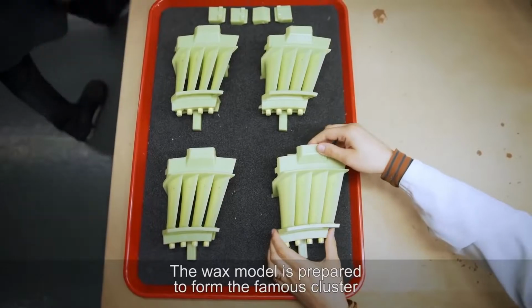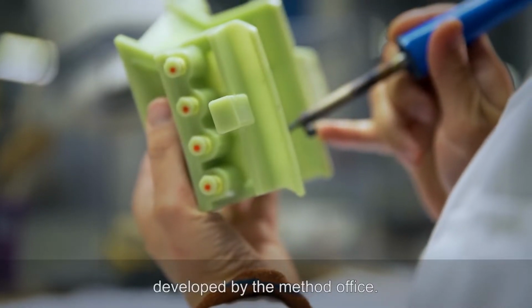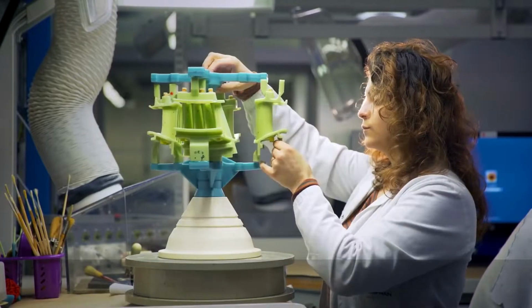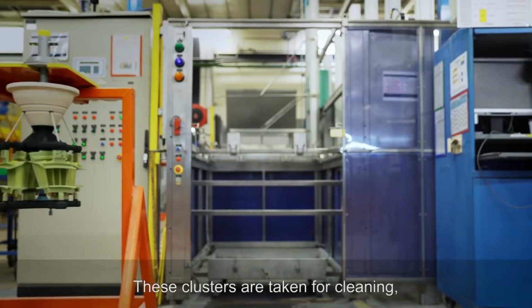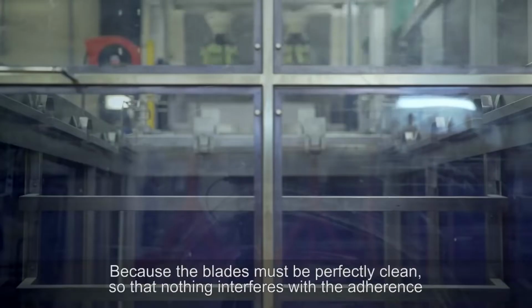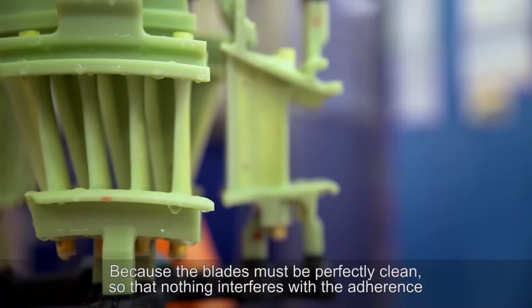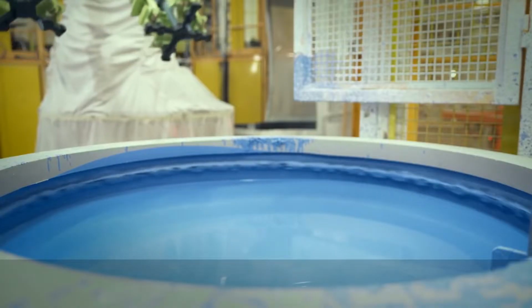The wax model is prepared to form the famous cluster developed by the method office. These clusters are taken for cleaning, which is essential to remove all traces of handling or release agent. Because the blades must be perfectly clean so that nothing interferes with the adherence of the material, they will be covered in the ceramic slip.